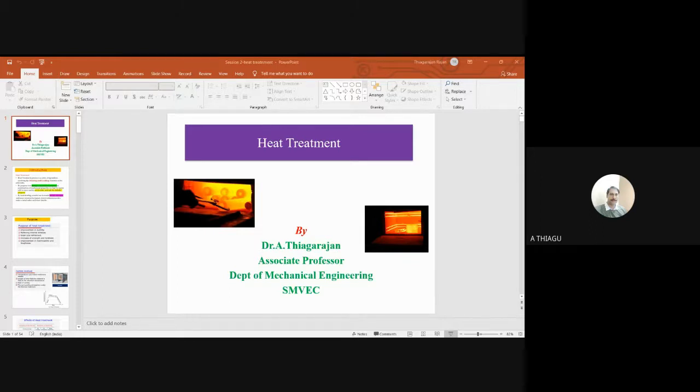For nitriding, nitrogen should be deposited, and the most suitable applications are aerospace engine components, engine cylinders. The temperature will be 500 to 550. The last case is the carbonitriding process, where carbon and nitrogen should be deposited from ammonia gas and propane gas or methane gas. So for different applications or your requirement, you have to select the process.